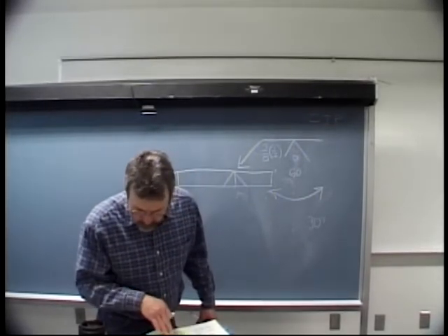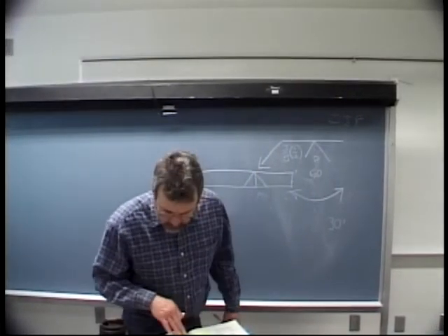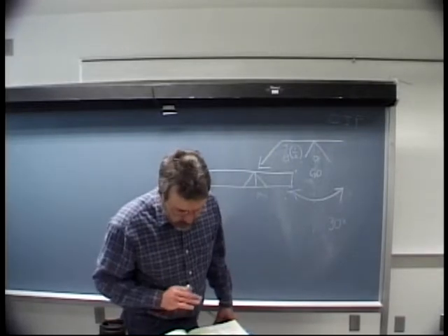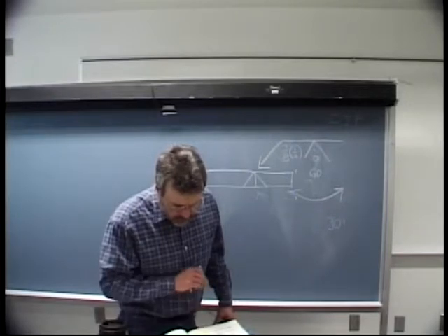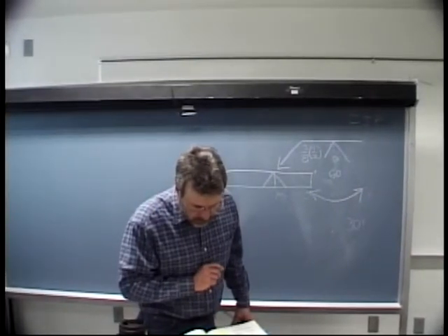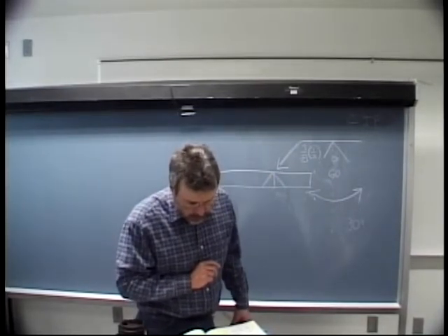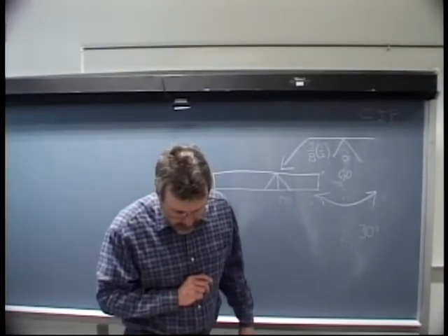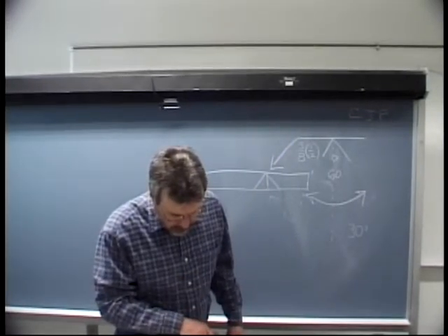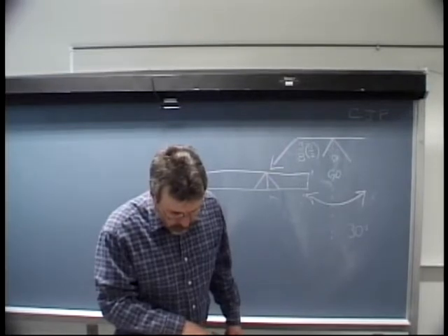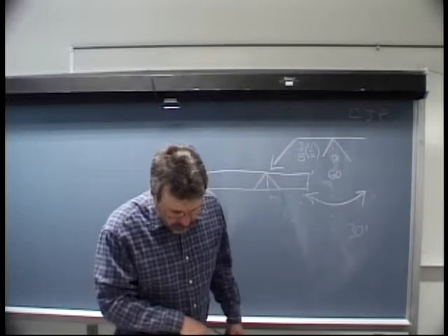And figure 3010 is off to the right-hand side. That's just what I was talking about on the board with my other slide. Again, my slides don't match up with your textbook quite exactly, but the examples are similar. Drop down a couple of sentences and highlight where it says, since groove welds and butt joints are typically used in highly critical applications, they generally will be required to run the full length of the joint. Drop down a little further, it says, if a groove weld length is required, it will be shown to the right of the groove weld symbol. If no length is shown, the weld shall be made the full length.